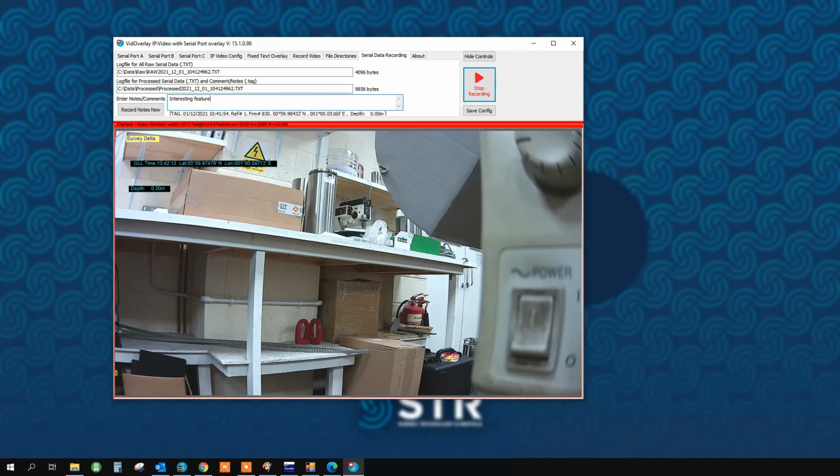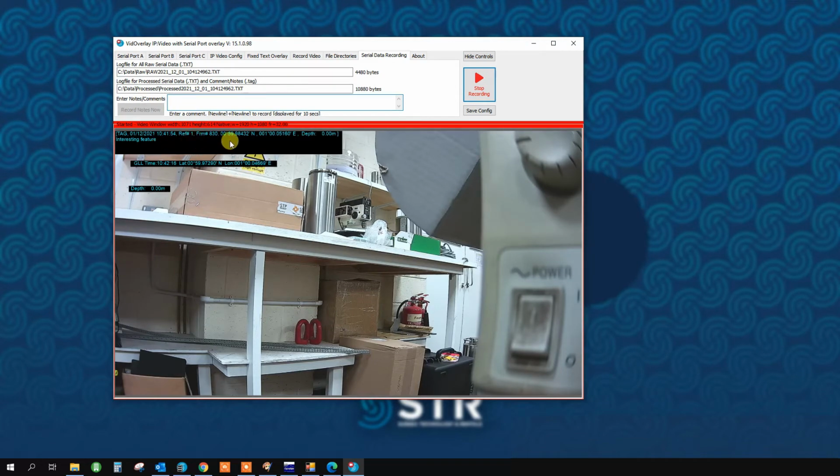And double press return, and this will then appear on the overlay along with GPS, time, date and sensor information, and it appears for a fixed number of time, which in this case was 10 seconds, but from the configuration file can be adjusted. The text, font and overlay color can also be adjusted from the INI file too.